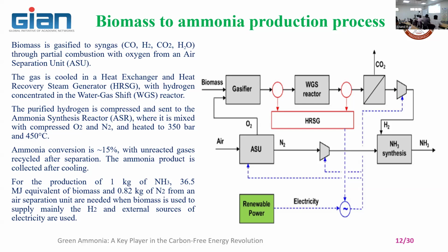Whereas for finding out the calorific value of the synthetic gas, syngas, we can take it to the GC. We have the onboard GCs available. You can use it to find out different hydrocarbons, then find out the energy content, or you can go for Junkers gas calorimeter.